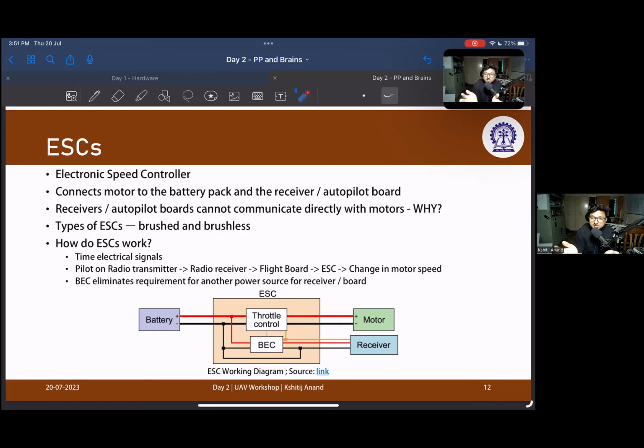However, the brushless DC motor is a three-phase motor. Okay, it has three independent sets of windings, which have to be powered in a timely manner, in an organized step-by-step manner, to make the motor turn. Okay, and since there are no rubbing parts, it's frictionless. Okay, it lasts longer, but we need a controller to run the motor. That is the drawback. You have extra hardware here now to control the motor.